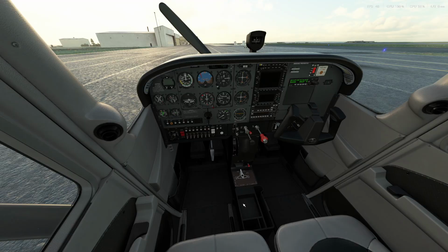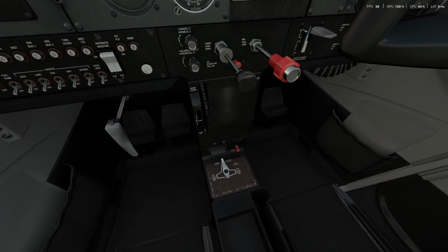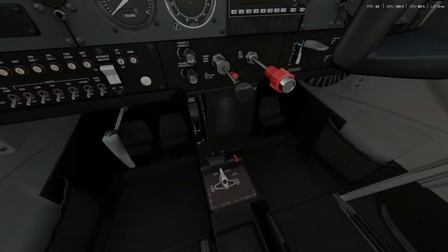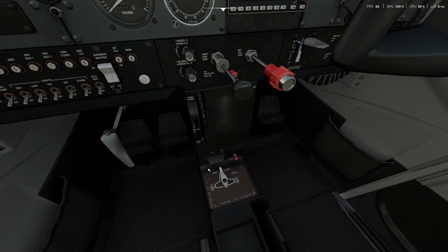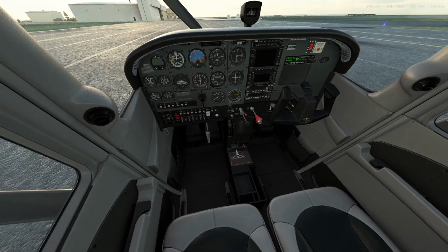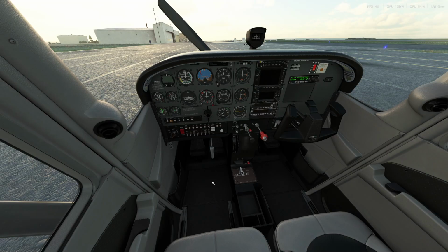All right, flight controls. Full left, full right, full aft, full forward. Flight controls check free. There's no resistance. Fuel selector on both. That's the guy down here. Fuel shutoff down there also, and it is in. Brakes are tested and set. All right, the engine starts with battery. Beacon on, flaps retracted, throttle open a quarter inch. Mixture idle cutoff, master switch on.